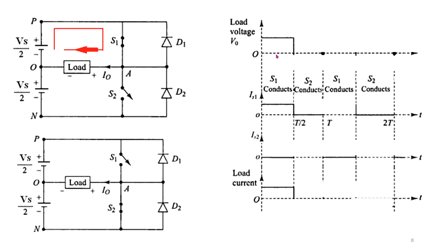What happened next? In the next cycle, the switch S2 conducts. Now the direction of the conduction, you can see that here the polarity is different as compared to the previous one. Now current is flowing in another direction, plus here, minus here. If we consider the load voltage, it is inverted as compared to the previous case. That's why it goes downward, and similarly the current.